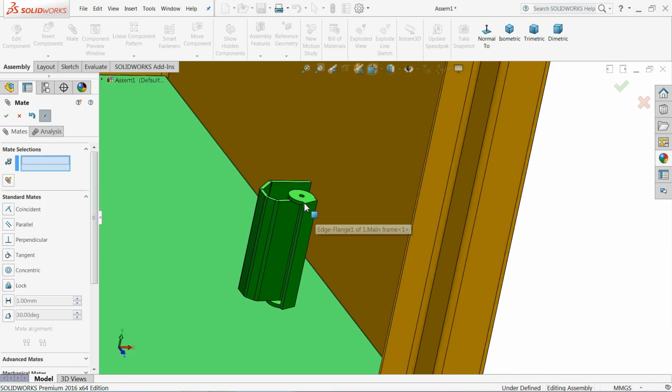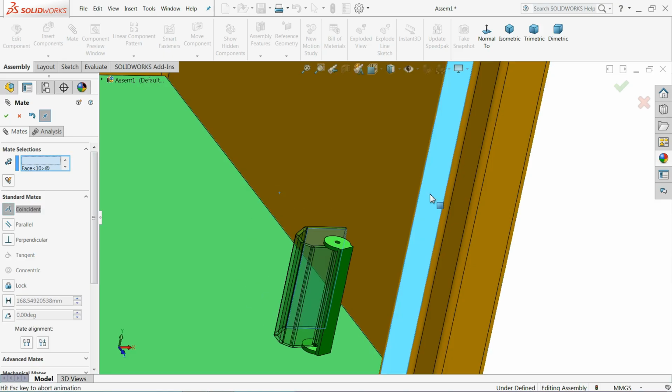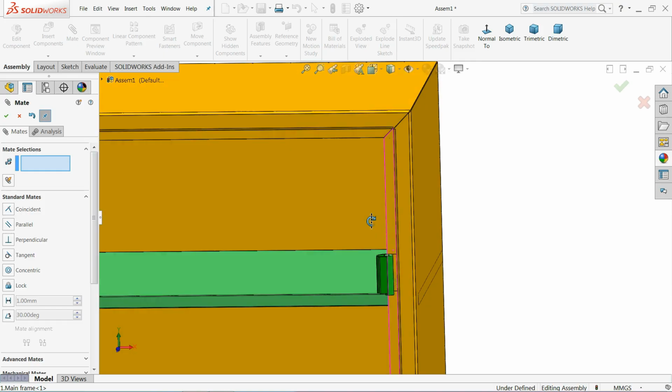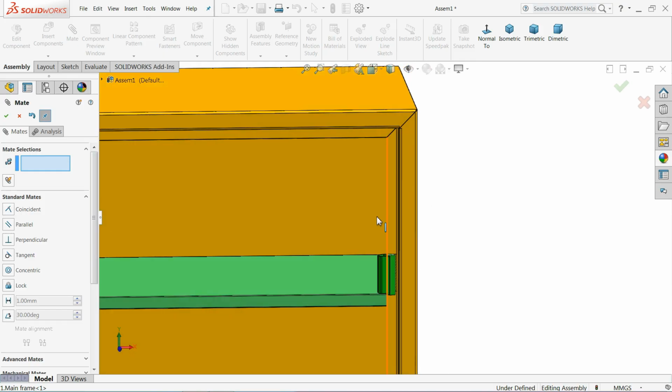Okay, now select this inside face and this face, make relation again coincident. Okay, now it's time to make some distance.